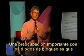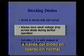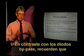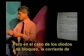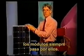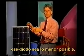An important concern with blocking diodes is that we always have a small voltage drop across the diode during normal operation. Contrasting to bypass diodes, normally they're not in the circuit, remember? Only in case of shading. But for blocking diodes, we have the case where current from our modules is always going through these blocking diodes. We want that voltage drop through that diode to be as small as possible.